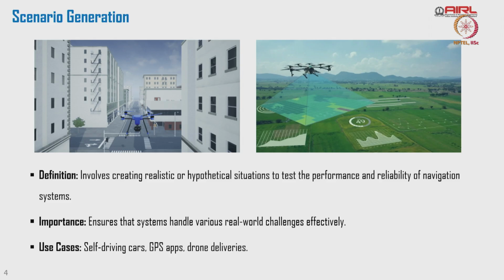If you are using a pitot tube, it measures the pressure with respect to mean sea level. If you are using a LiDAR to measure your height, it is going to follow the terrain height. What height do you want to maintain? Based on the application, you have to decide what sensor to use and what height you want to maintain.